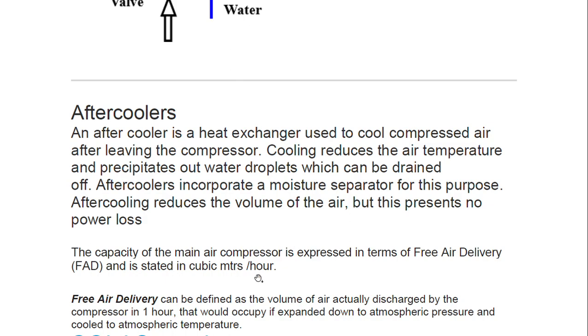and is stated in cubic meters per hour. So it is meter cube per hour. Okay, if we define free air delivery, it is the volume of air actually discharged by the compressor in 1 hour. From the unit only they are defining it. So the volume of air that is actually discharged by the compressor in 1 hour, that would occupy if expanded down to atmospheric pressure and cooled to atmospheric temperature.